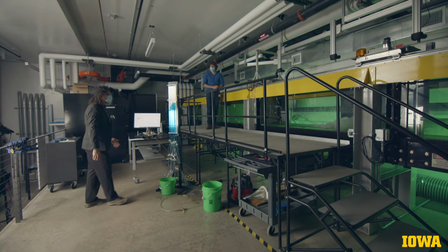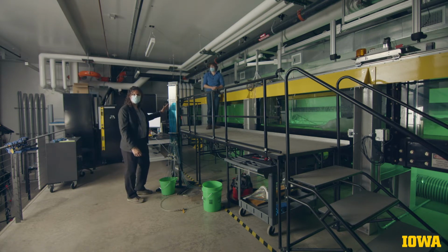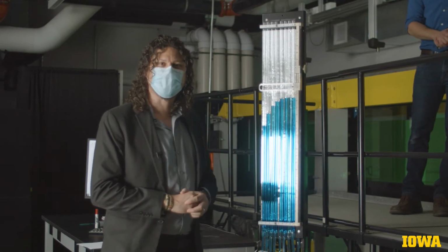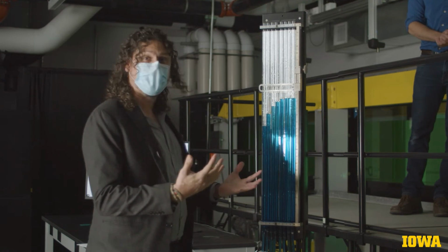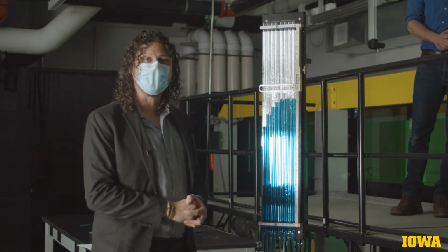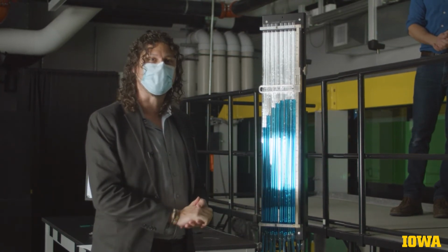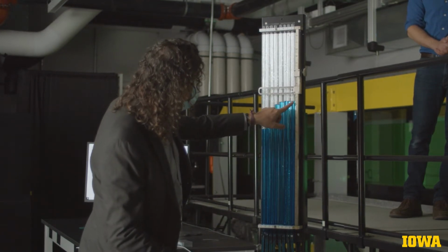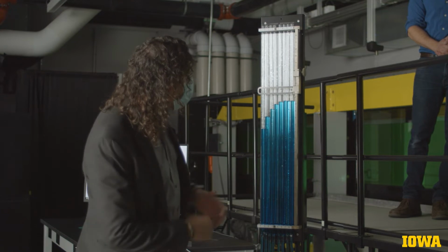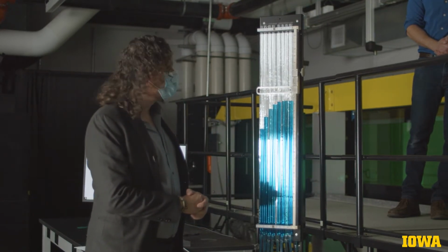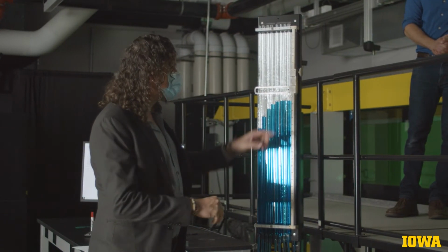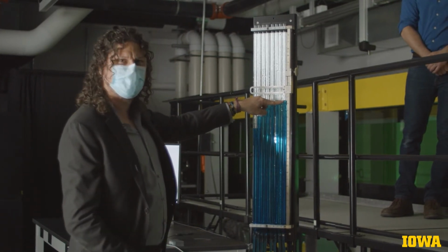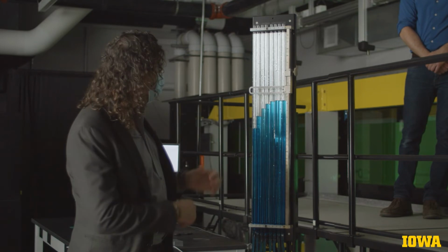So the piezometers are going to allow us to measure the pressure at different elevations in the gate, and they are going to provide the information we need to calculate the forces acting on the gate. One of the manometers is connected to a tube that is upstream from the gate. So what we expect is that this manometer is going to be giving us a reading of pretty much the elevation of the surface upstream from the gate.